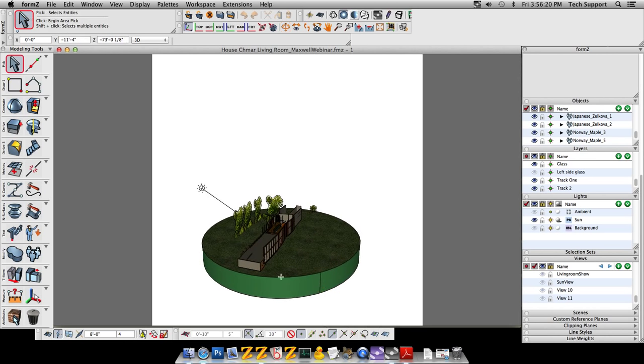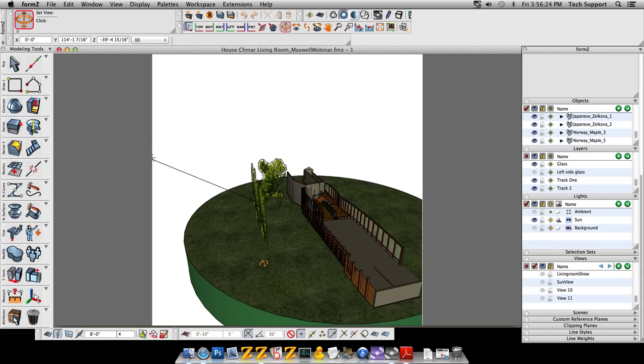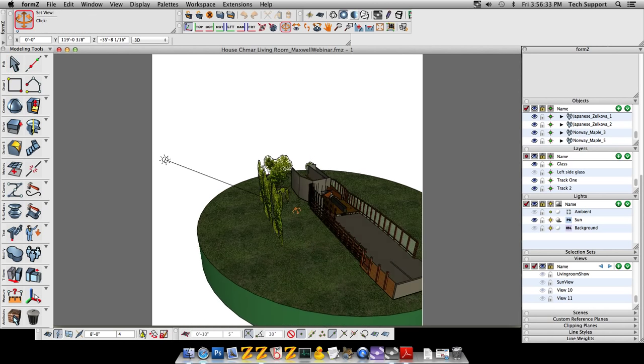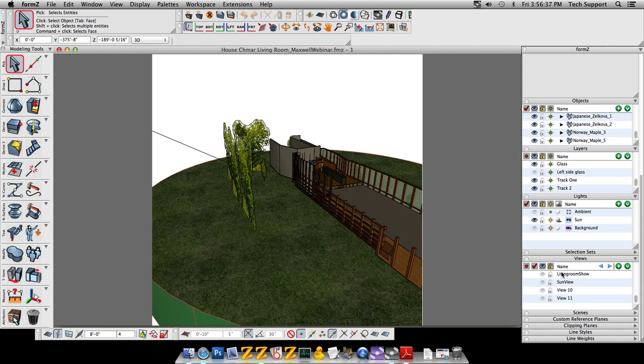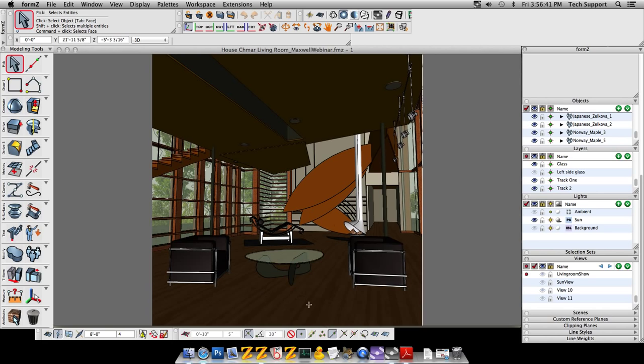So out of doors, we're going to have the same physical sky automatic setup that all of our other images have used. Now, I've added some of our component trees here so that as the light falls through the trees, they will cast dappled shadows onto the floor of my building here, and perhaps add some interest to an otherwise kind of boring area of my render.